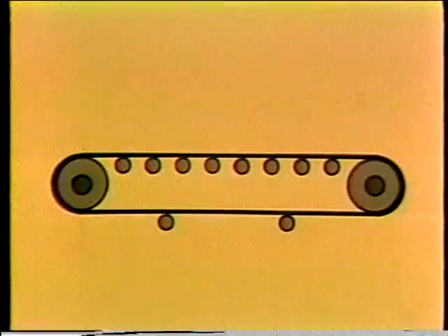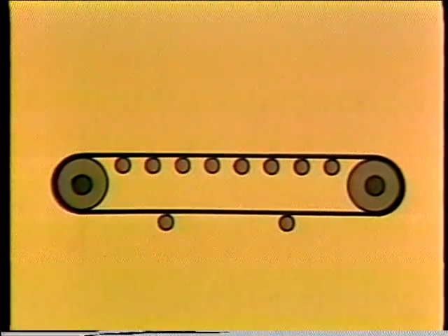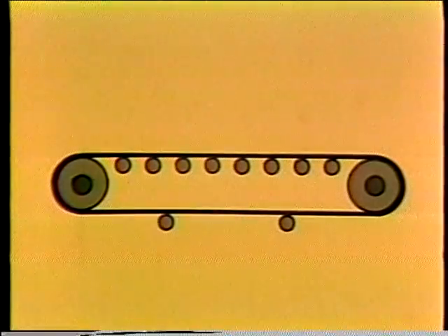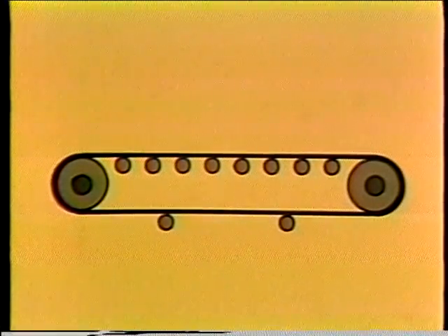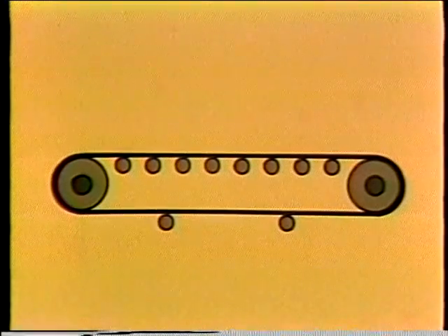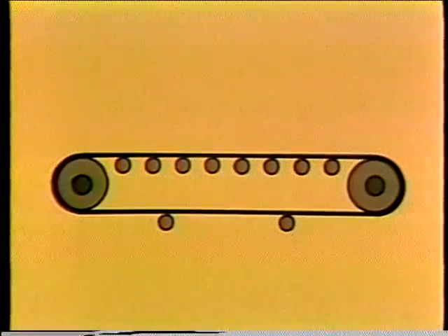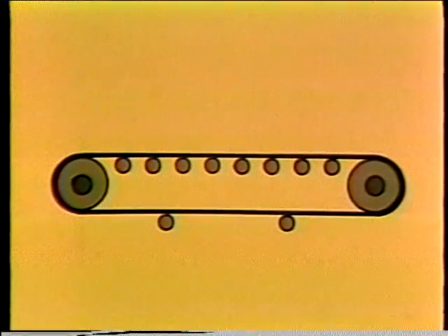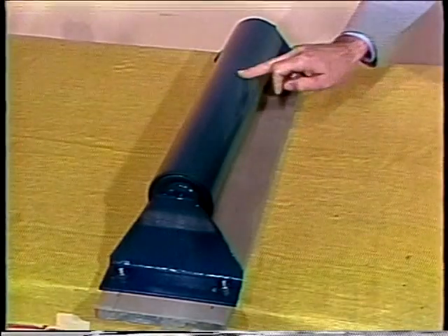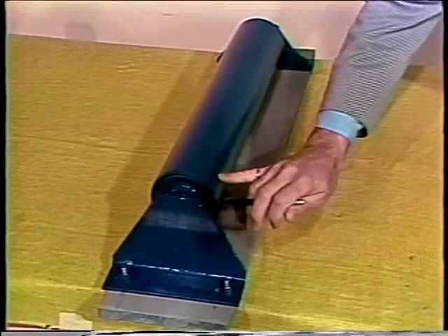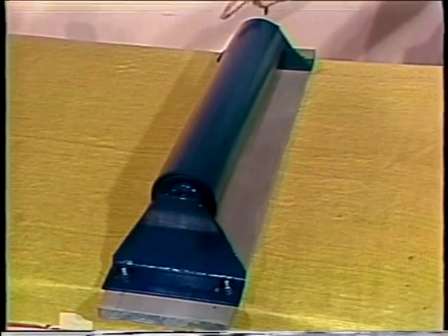As the belt conveyor becomes longer, some additional support is going to be required in the middle. This is done with idlers. These are cylinders of steel and are normally 4, 5, or 6 inches in diameter. The length of the idler is determined by the belt width. They have a bearing in each end, and these bearings may be either ball or roller bearings, depending on the load the conveyor is to handle.